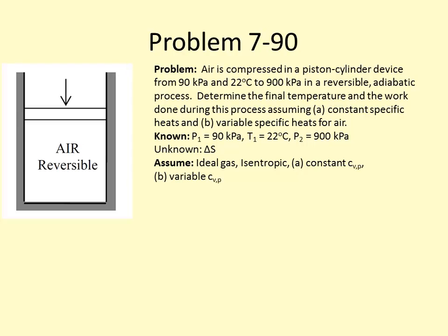It's the theoretical limits. Okay, the theoretical limit, so it's the isentropic case. So anytime in a problem when it says the maximum work output or the minimum work input, you can assume they want the reversible case, and if it's a reversible problem that's also adiabatic, then it's isentropic. Okay, so they don't always tell you this is an isentropic problem. You have to look for those keywords in your homework as you do it.